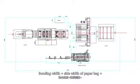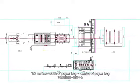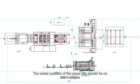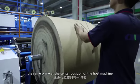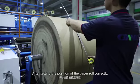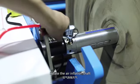Bonding width plus side width of paper bag plus half surface width of paper bag equal to center of paper bag. The center position of the paper bag should be on the same plane as the center position of the host machine. After setting the position of the paper roll correctly, inflate the air inflation shaft.